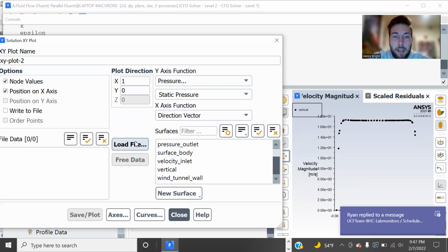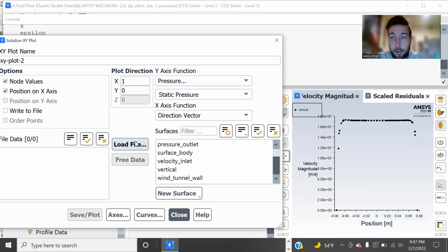That was very helpful. And then for finding the dynamic pressure, do basically the same thing, create another line that's horizontal through y equals 0 from beginning to the end of the test section. And then I actually just averaged those because it wasn't constant. Hypothetically, it probably should be, but being a viscous turbulent flow, it's not going to be. So that was the easiest way I felt to do that. So I did that, and then I plotted.